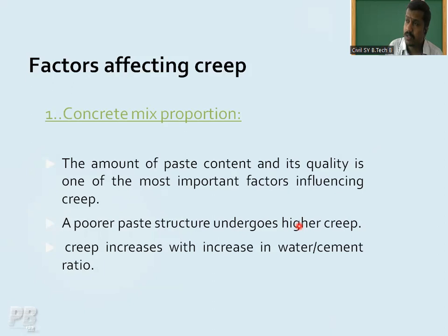See, if you are going to take a faulty mix proportion design or improper proportion of your concrete ingredients, what will happen? The structure is not durable. Maybe you have used excess cement, which causes early cracks in the concrete. Again, I am repeating my same instructions.